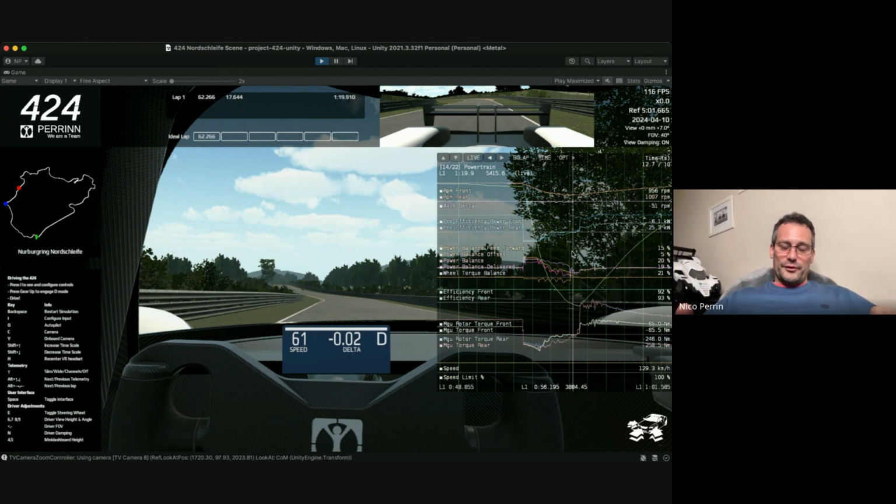So all of that torque, or 85%, is at the rear. So it's a little bit like pulling the handbrake gently, just to let the car rotate a little bit. It's a nice little effect that helps the car rotate. And as soon as we touch the throttle, the balance goes back to the front. So we were at 15%, and now we're going back at full throttle.